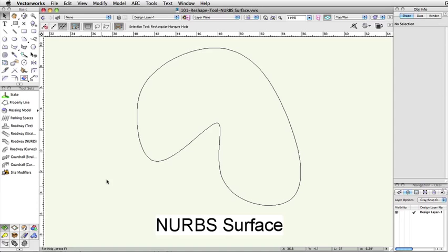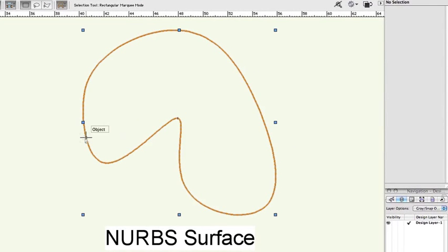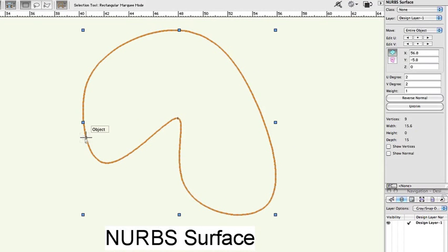The X, Y, and Z axis constraints do as you would assume, allowing the motion of the vertex in X, Y, or Z respectively, but in no other axis while that constraint mode is active. If you suddenly find yourself unable to modify vertices in more than one axis, make sure that one of these modes is not enabled. When modifying NURBS surfaces specifically, you have a few different methods of control.